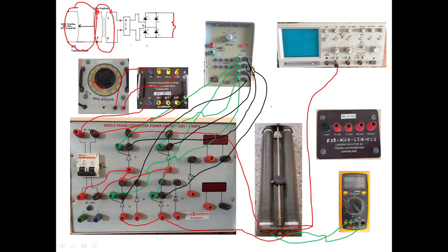Now coming to the operation part, first you have to give 80 volts here. Once you give 80 volts, you have to switch on the MCB, and then this is your firing pulses. First you have to keep that at 0. You can start from 0, alpha equal to 0. Then you have to observe the waveforms in the CRO, and see what the voltage is here, and make sure this multimeter is kept in DC mode. Then you have to measure the voltage and note down the practical value, and the theoretical value you have to calculate using the formula, right?